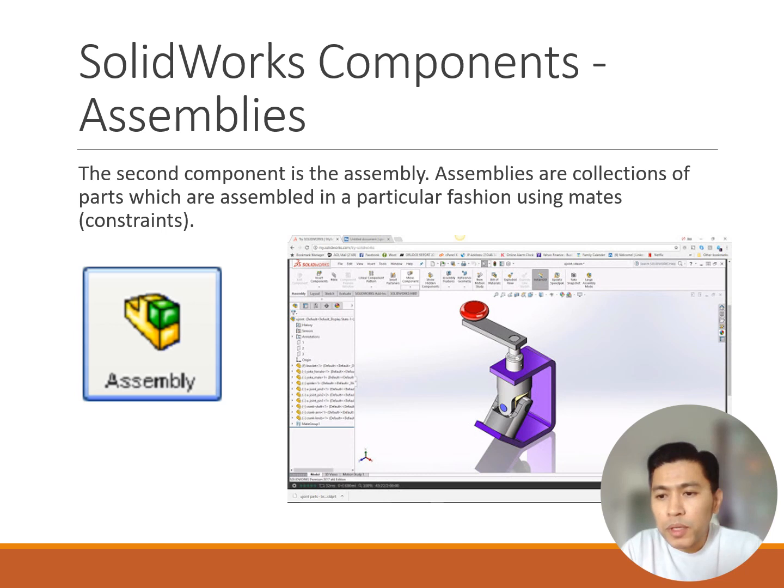In assembly mode, individual parts are assembled using mate tool relations into a complete model. In assembly mode, models can be animated using a motion study tab and evaluated using the command manager tab, offering tools for collision detection, interference checking, and physical simulation of assembly motion.